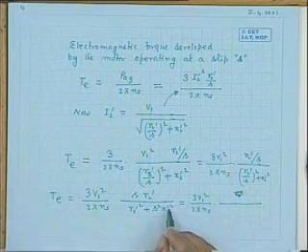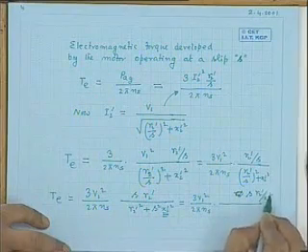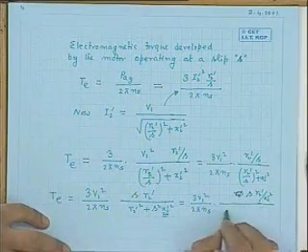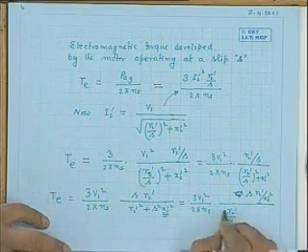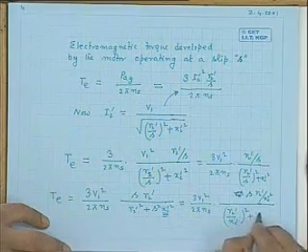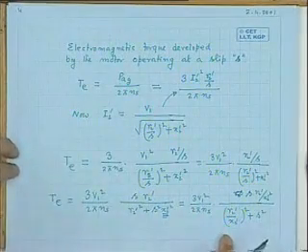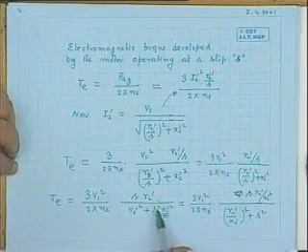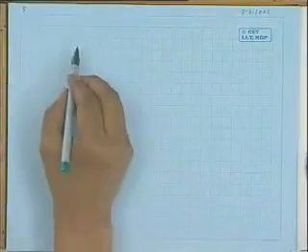Oh, this will be same. So anyway, this is okay. Now you divide by X2 dashed squared, both numerator and denominator. Then it will be S into R2 dashed by X2 dashed squared in the numerator, and in the denominator it will be R2 dashed by X2 dashed whole squared plus S squared. It is correct. So this will be this expression. At this step, you divide by X2 dashed squared in numerator and denominator.